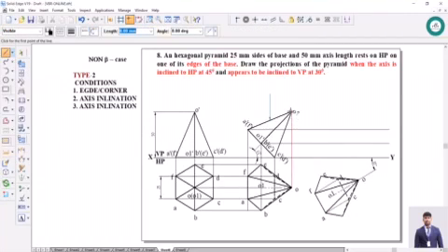Further, you can continue with your projections. So we know that the resting edge always falls on the XY line. With that knowledge, you can directly project this. Next, this E point somewhere falls on the second line. So this is your B point.